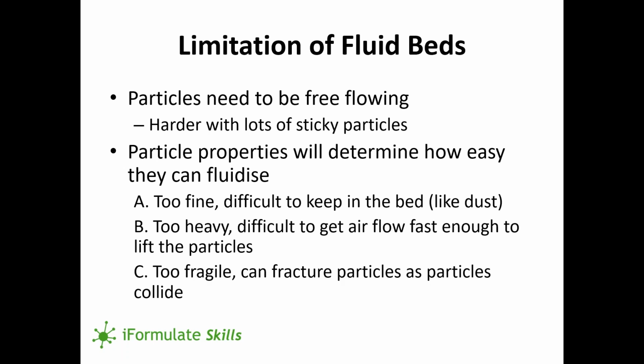And then finally, if the particles are too fragile, the movement within the bed has to be carefully controlled, because what you don't want is to fracture the particles or to erode the surfaces and create fine dusts. Because those particles are going to collide, you need to be careful about breaking the particles up.